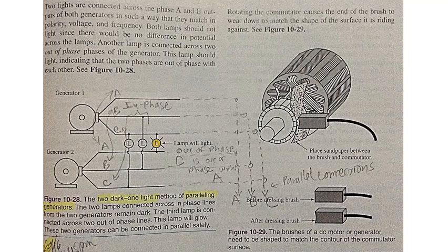Excessive bearing wear. Worn bearings will cause a roaring sound. Excessive vibration can also be present. Another sign of excessive bearing wear is a shiny spot appearing on the armature. This spot is caused by the armature rubbing against a pole piece as the bearing wears out.